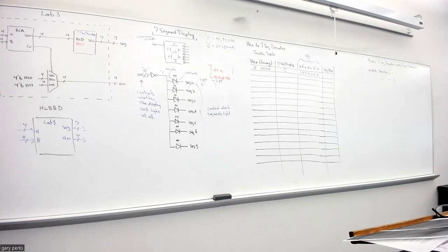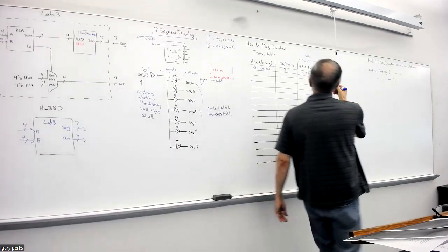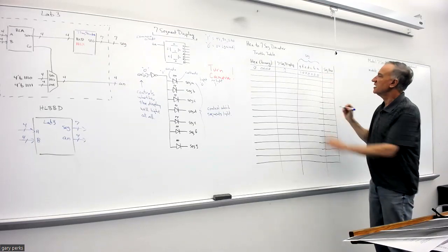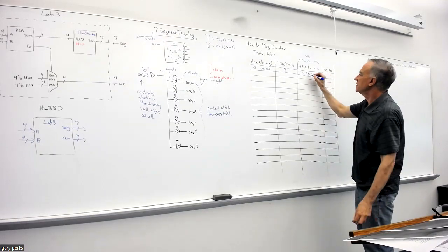Here we went from hex to binary by writing each hex character as a 4-bit binary group, but you can go the other way. Take 4-bit binary groups, always starting with the least significant bit, and write each 4-bit group as a hex character. I would start here, and that gives me 0.